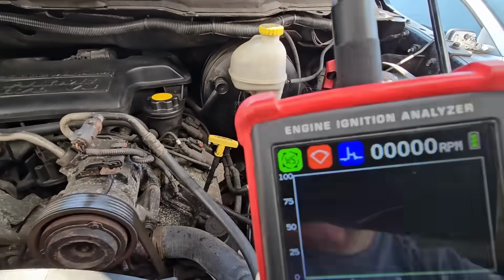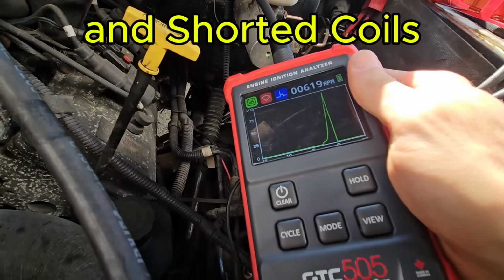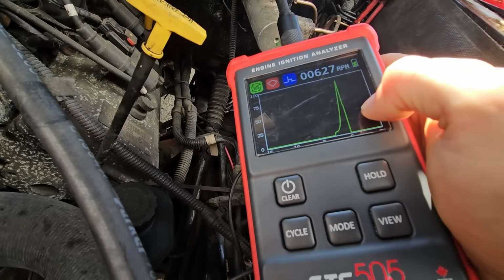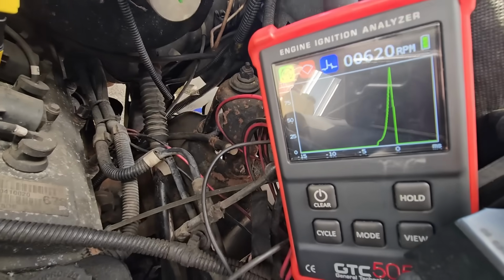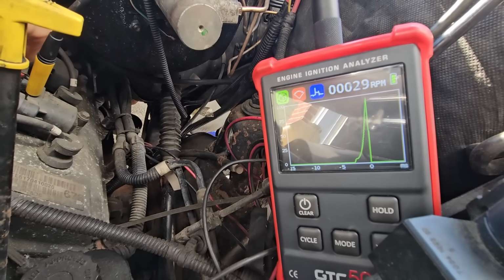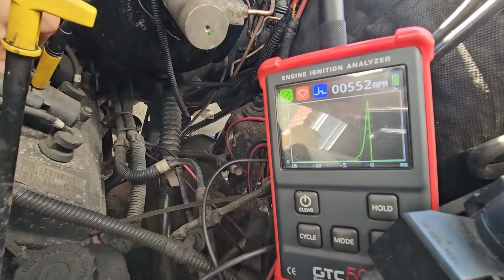Now going on ramp time, this is showing us how long that coil is being commanded on. So you can use this to catch intermittent power drops or signal drops. If you had a connection issue, you would see a dropout in this line. So let me see if I can show that to you. So we see we have our coil there. I'm going to unplug this, and we see how it kind of freezes and then drops out. When it freezes like that, it's not getting any more. And if I slightly pull it out, you can see that that command is a lot shorter.